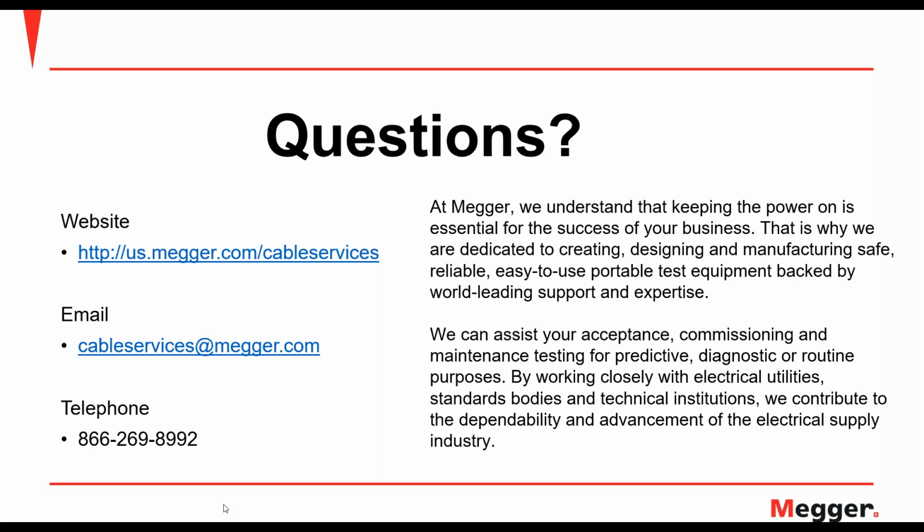So while it can be used to predict failures in that sense, there's also the other aspect, which is a limitation of tan delta, which is why we do partial discharge testing, and that is to find the localized issues. What I mean by that is, if you had a local weak spot in your cable and the rest of your cable was pristine, then your tan delta measurement could reflect to be very good, right? But indeed, you do have a severe defect along that cable, which could lead to a fault failure. So while it can be used to predict failures, it's more or less to determine the overall condition of that cable's insulation system. Really, you want to use partial discharge testing to determine if there's any localized weak spots.